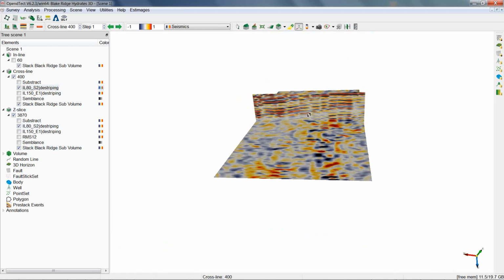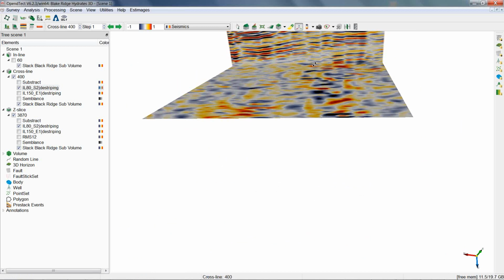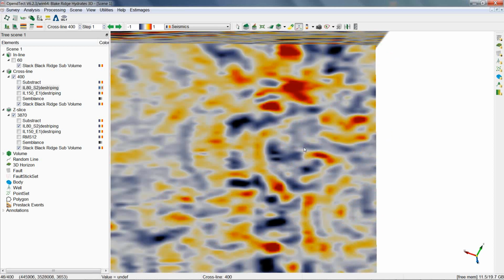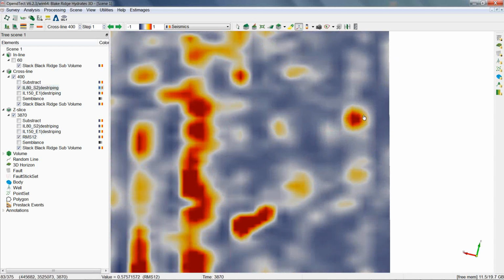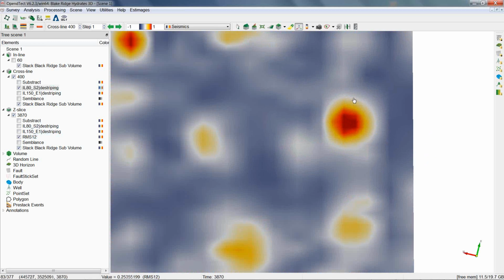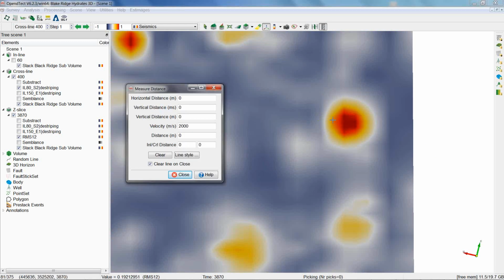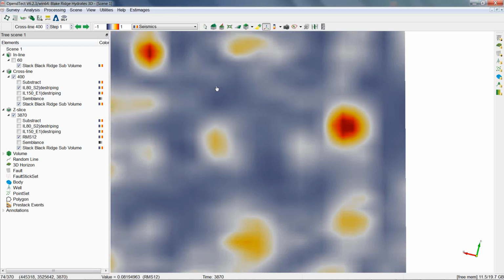A quick side note, when you're facing isolated patches of noise and the periodicity is not clearly visible, you can measure the half period on the patch which directly equals the footprint width. This is how. From one side of the patch to the other, identify the jump between two minimum variable values. The measured distance here corresponds to the semi-period. Write down that figure and enter it in the footprint width parameter required to filter.